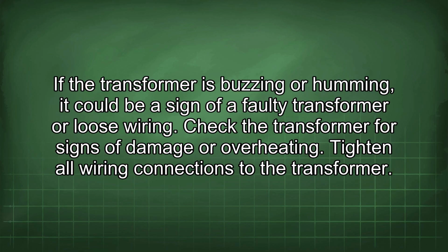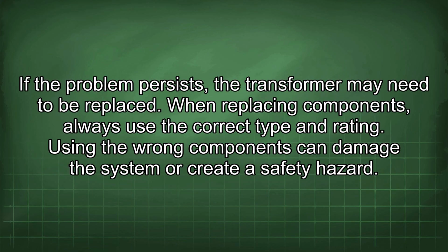If the transformer is buzzing or humming, it could be a sign of a faulty transformer or loose wiring. Check the transformer for signs of damage or overheating. Tighten all wiring connections to the transformer. If the problem persists, the transformer may need to be replaced.